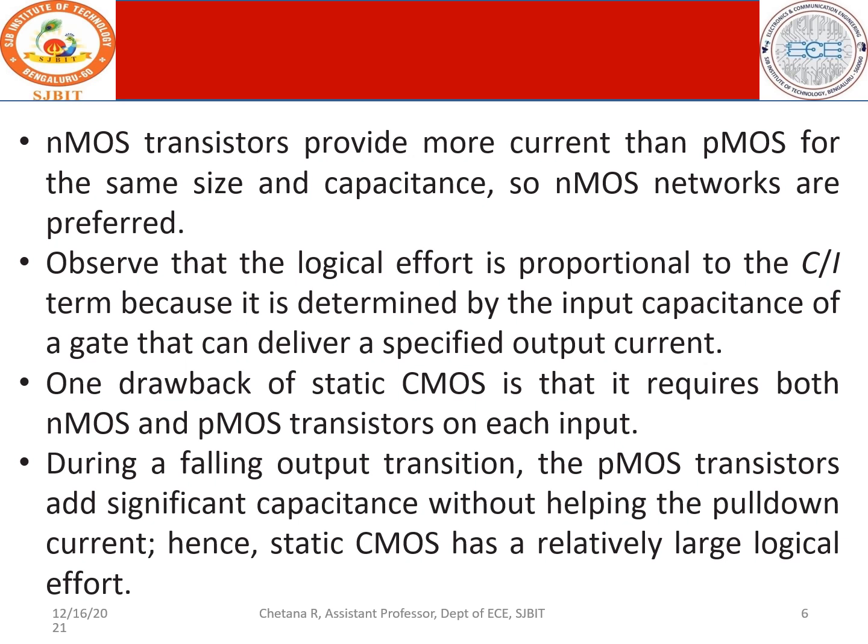So during the falling output transition, that is from 1 to 0, the PMOS transistors have their capacitances, and therefore static CMOS has a relatively large logical effort.